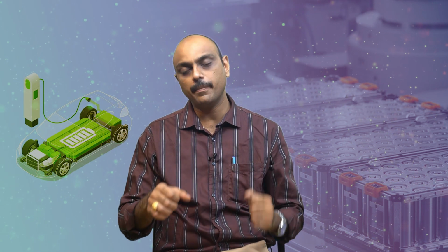So, when the complete battery is immersed in the liquid, there are various other alternatives or concerns that are to be taken care of. The first one is the coolant, whatever we are using. It should have a very high thermal conductivity and thermal capacity, and the viscosity should be very minimal. This figure shows you what immersion cooling is, or how this immersion cooling works.